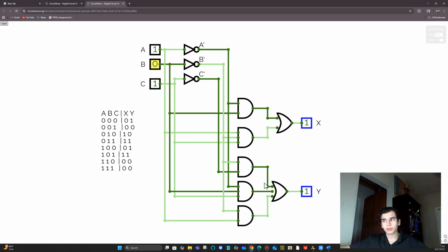So that's what a combinational circuit is. It's something that changes instantly, like its outputs are automatically updated when the input changes. That's all a combinational circuit is. And every combinational circuit can be represented in a table. Some of the tables are too big to write by hand, but they technically can be in a table if you were to spend an eternity specifying all possible combinations. But in this example, we're going to go over the ones that are small and can be modeled in a table, which is a large portion of the combinational circuits that matter.